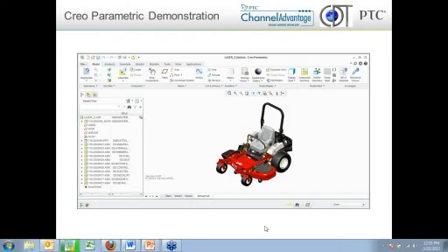Okay, and using the skeleton, how do you create the attachment points? Well, there's a lot of ways. There's actually a training class that goes into this. I can't give you a really good answer quickly and easily, but there are multiple ways to create those attachment points. If you're creating a skeleton model, in the case of that piston that I showed you earlier, then I can specify just a point on a circle as being the rotation of that crankshaft. But there are multiple ways to specify those attachment points.